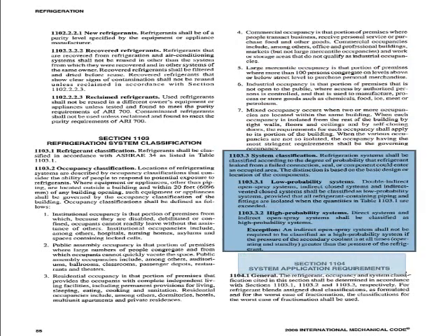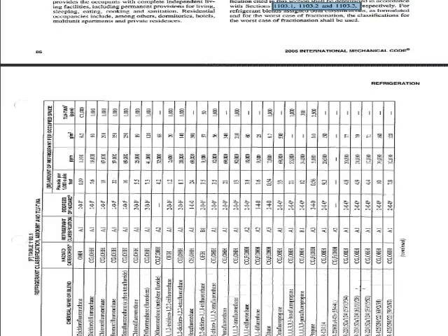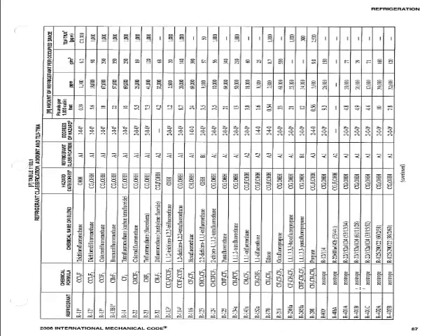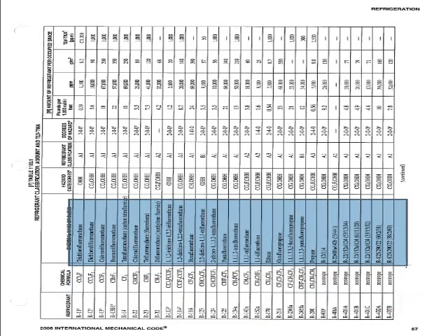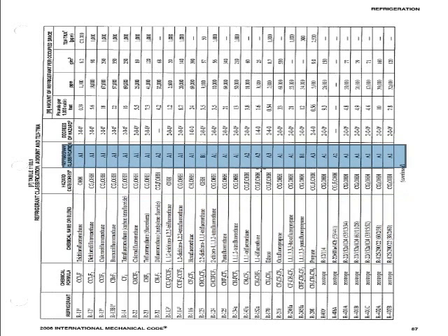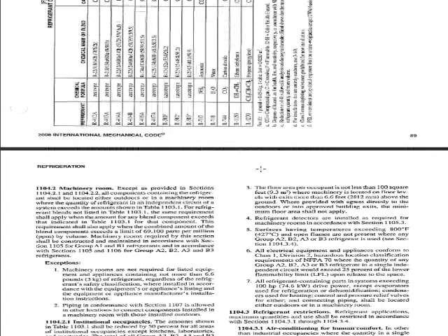1104 talks about system application requirements. There are some general requirements that refer back to 1101 and 1103, but then it moves on. You will also find in here tables that give you the chemical formulas for every various type of refrigerant out there. It gives you the chemical formulas, the chemical names, and it also tells you what's in any blended refrigerants. And it gives you the refrigerant classification, the safety classification. Remember, A is non-flammable, 1 is non-toxic. So you have a couple pages of those charts.